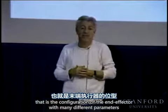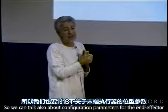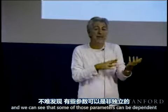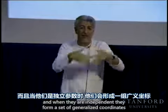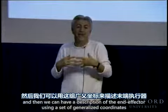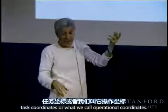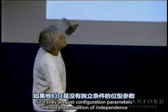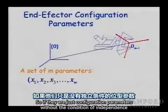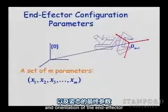different parameters. So we can talk also about configuration parameters for the end effector, and we can see that some of those parameters can be dependent, and when they are independent, they form a set of generalized coordinates, and then we can have a description of the end effector using a set of generalized coordinates, task coordinates, or what we call operational coordinates. So if they are just configuration parameters without the condition of independence, then we can talk about these M parameters describing the position and orientation of the end effector.